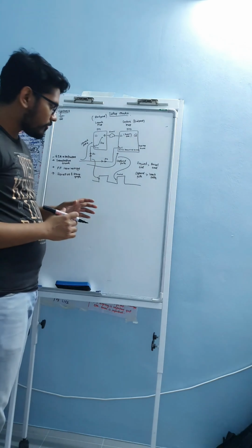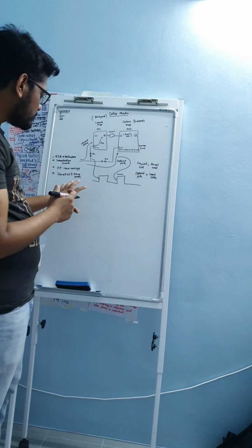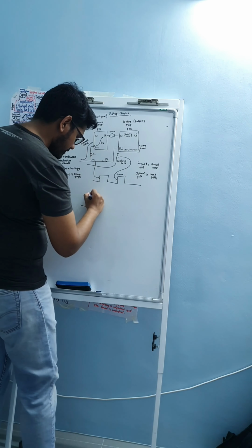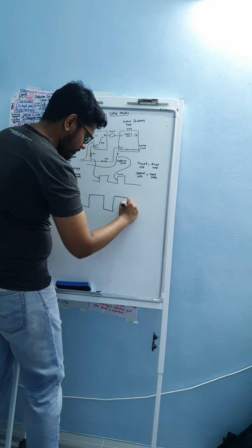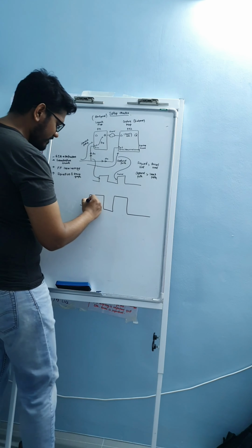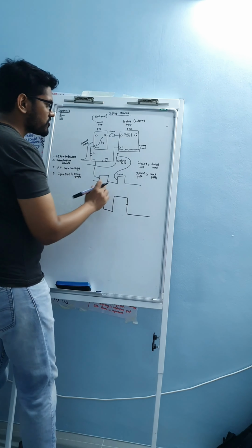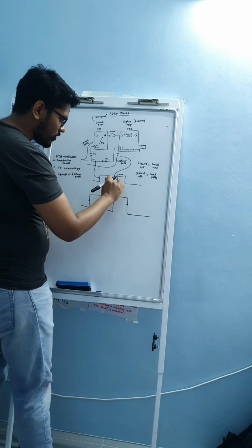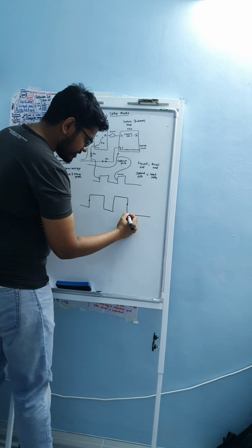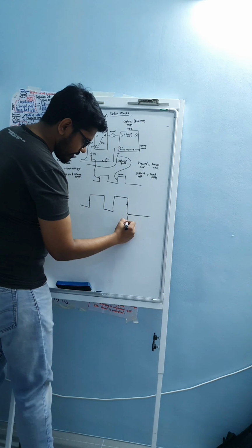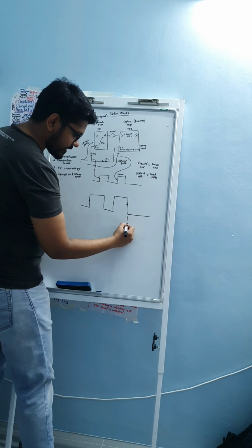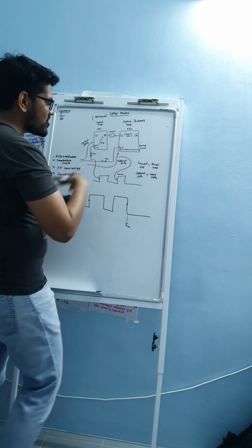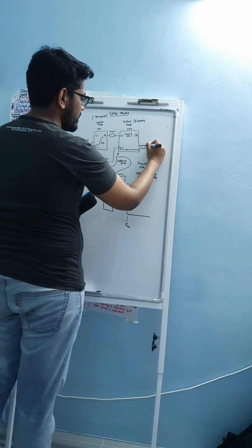Alright, let's move on and draw another new timing graph so that you guys have a clearer picture here. I've mentioned to you earlier that for setup checks, your timing check is going to be on your next clock edge. So over here is your timing check for the setup. But then you have to remember, we have a T setup of X value.